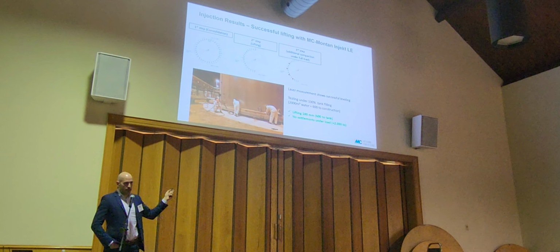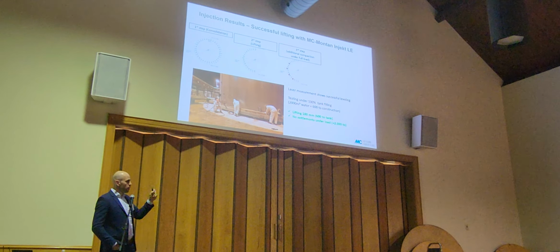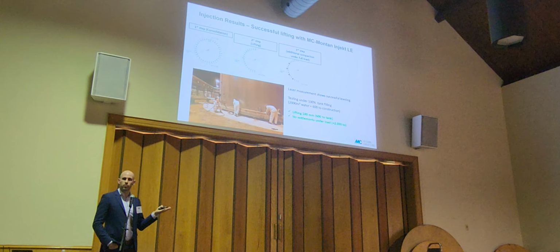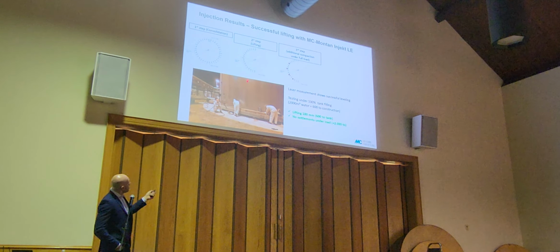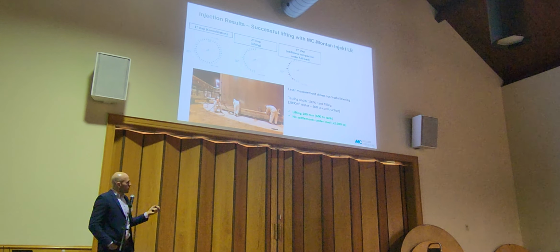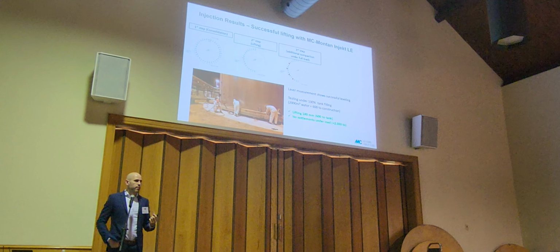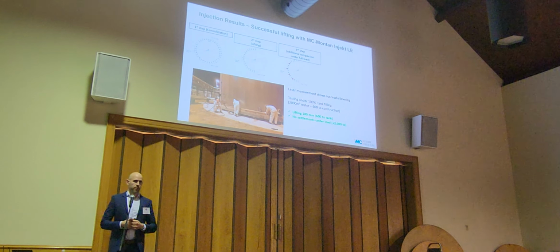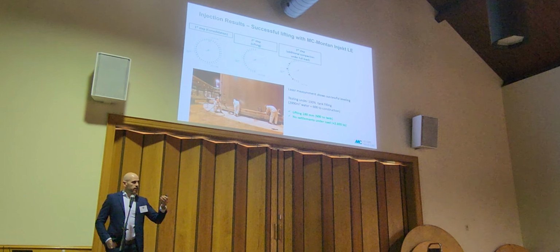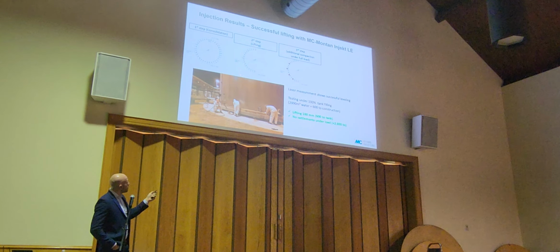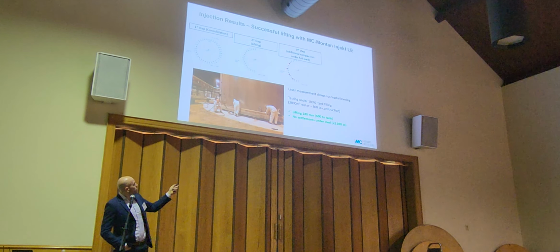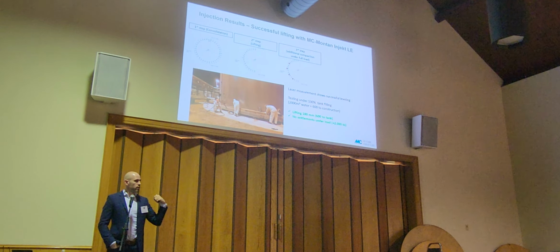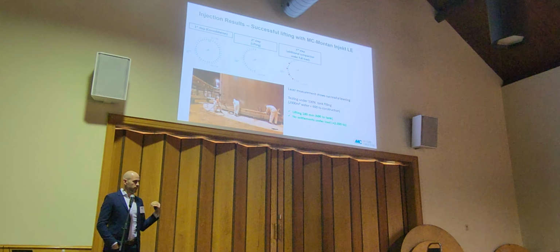And in the second step, here the purpose is to lift, and 18 centimeters, okay, you have a lot of time until you reach a critical point where you have to be careful. But in this step, the only way is up. Why? Because the soil around was already consolidated by the first step. So once the lifting was done to the initial level of the tank, they said, okay, we need to prove somehow that once you fill your tank with 2,000 cubic meters of water, it will not settle again.